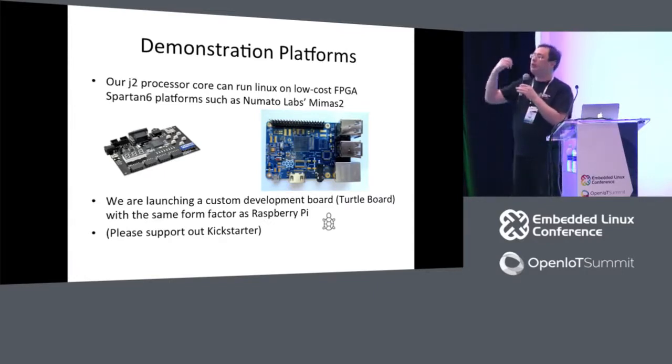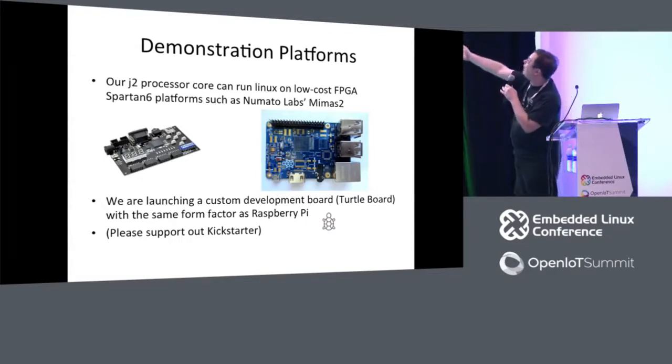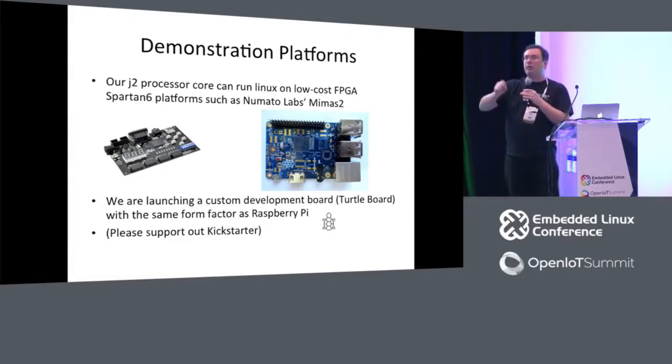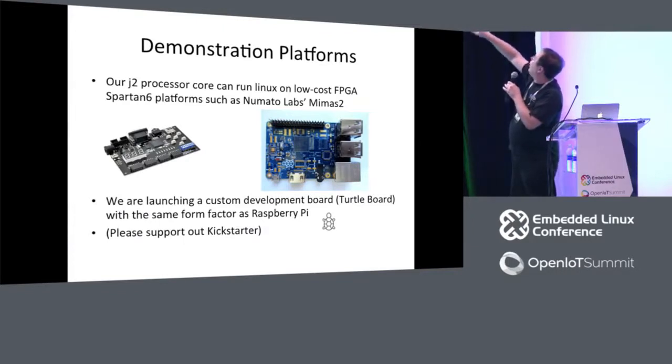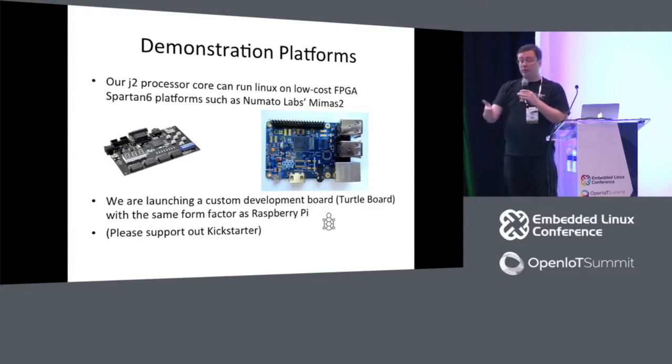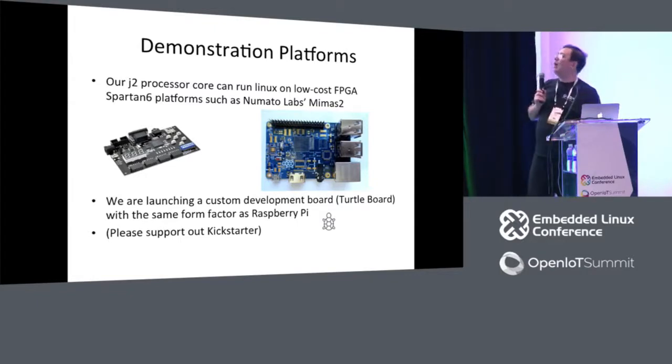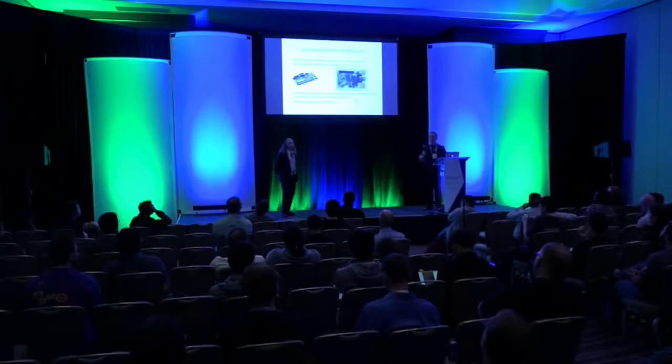So we will need an FPGA implementation of HDMI. We will need an FPGA USB 1.1 controller. You can't easily do USB 2.0 in an FPGA, but we can. There's tricks we're pulling. Bunch of GPIO pins, Ethernet. That has Ethernet. Ethernet opens a world of things you can do. It's a really nice board, and we will link the Kickstarter from the jcore.org website when it goes live. So not only the Gerber files will be open, but the schematics as well. And if you want to build those boards, please have at it.